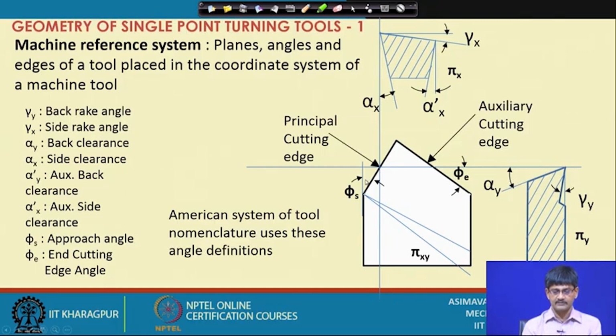Approach angle is sometimes called side cutting edge angle, and this one is the end cutting edge angle. When we have defined these, then the tool is defined in relation with the three machine reference planes.